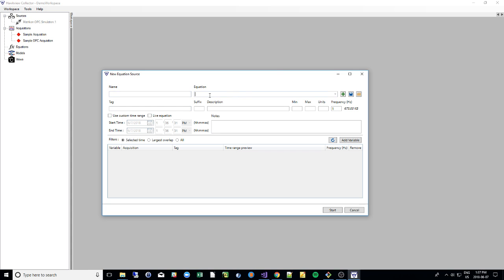You also have the equation parser, and this is just a text parser that takes a text and then through a series of checks will turn it into an equation that it will use to generate your output. The parser also has a syntax check, so if you just type anything in here, you'll have your errors pop up on the top. So here, error position 1, unknown word or invalid number format. It does not recognize this, but if I put in a number, it recognizes the number. 6 plus 9, that'll give me 15 at every sample point. It's very dull, but it is a functioning equation and it will work.